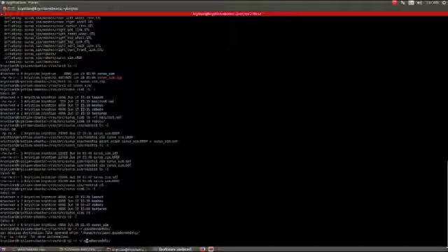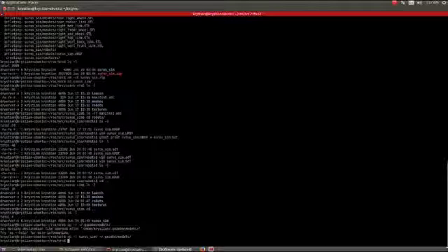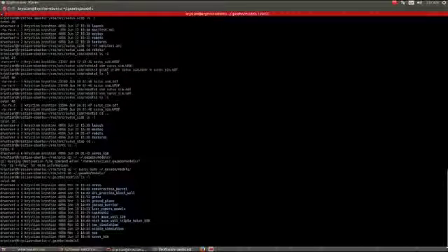I need to copy. Okay, so now we can go. By default, the .gazebo/models folder is the environment variable in the Gazebo resource path, or the Gazebo models path. This is where Gazebo loads all the models that you can insert manually by clicking and placing into the Gazebo world.